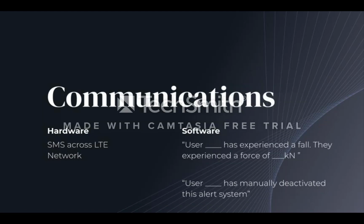Now we'll be discussing the communication system. From the hardware side, our device uses a modem and SIM card to send SMS texts over the LTE network. With respect to the software, when a user is in distress, the system will send an SMS text every 30 seconds until the user has determined they are no longer in distress. When a user has determined they are no longer in distress, the system sends an "I am safe" text message, which indicates the user has manually deactivated the alert system.